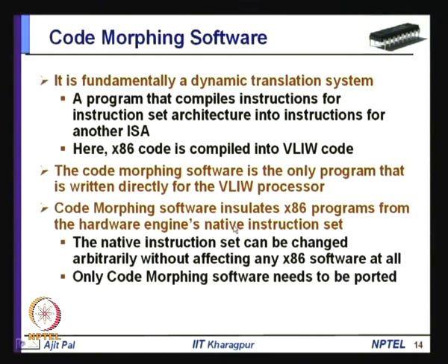Now, you may be asking, if VLIW is so advantageous, why has it not been used earlier? The concept of VLIW, very large instruction word architecture, has existed for a long time, but it was not popular. The reason is that when the task of writing code for a VLIW processor is given to the user, it becomes a very difficult task. That means, the user cannot handle the complexity of writing code for VLIW architecture processors.